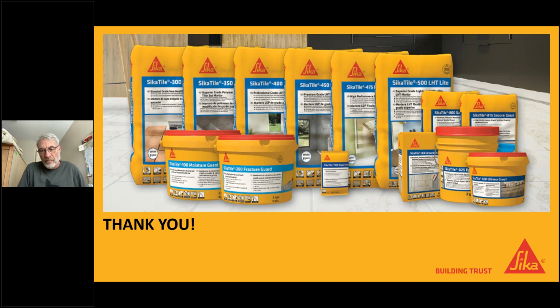Sorry about that. For the resin mesh back Rojo Alicante tile, what are your thoughts on a primer and an LHT A118.15 mortar instead of an epoxy mortar? There are some primers out there. We have one, and I know some other manufacturers, these multi-purpose primers that have an aggregate built into it, and they're made to go over impervious surfaces. We've had people use the primer on the back of these, and then use a modified LHT type of mortar, 118.15 or 118.11, to do that.